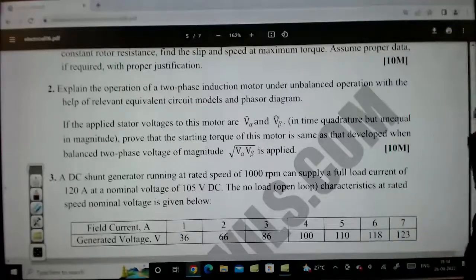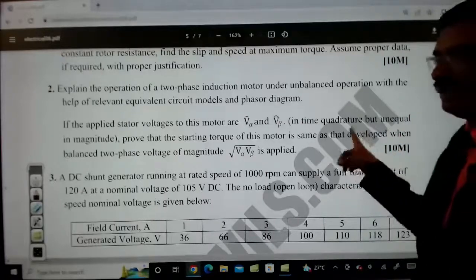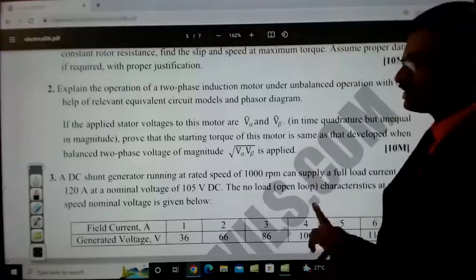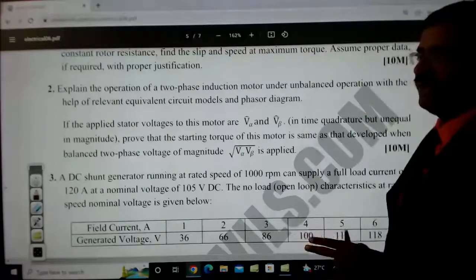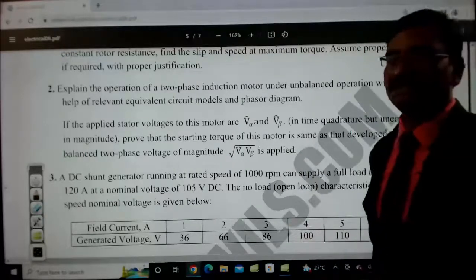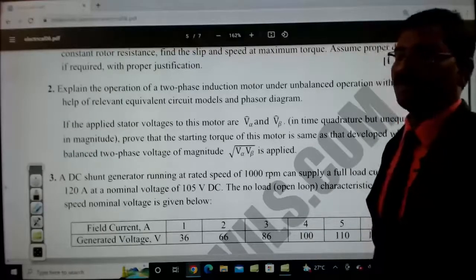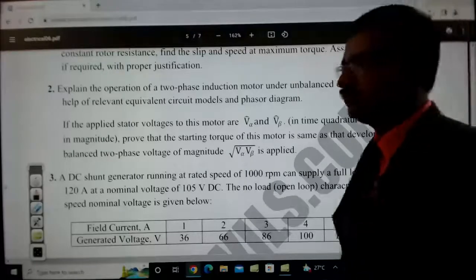So this is the concept of a single phase machine. This is a single phase machine, but it is converted into 2 phases, because a single phase machine directly cannot generate a rotating magnetic field. So to make it a rotating magnetic field, we are using a 2-phase system.